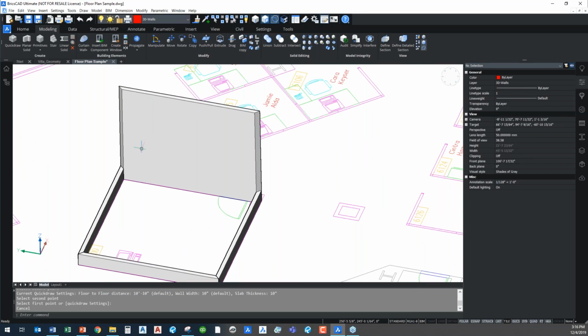All right, let's say I wanted to cut out a window opening. Through here, I had a big row of windows that I wanted to be 2 feet off of each side. I can use the standard offset command, and I'm going to set it for 2 feet. And I'm just going to offset this edge. See, it's setting it off 2 feet in, and you see it just offset the edge line so that now I've got a boundary in here.